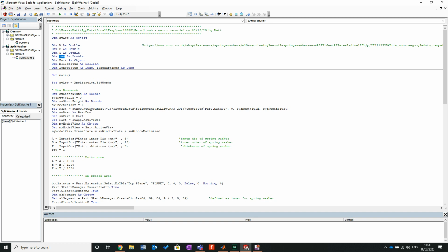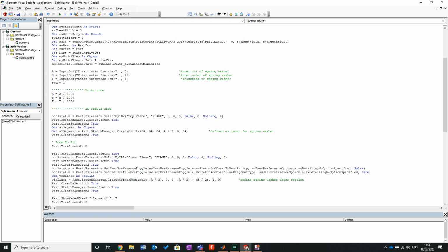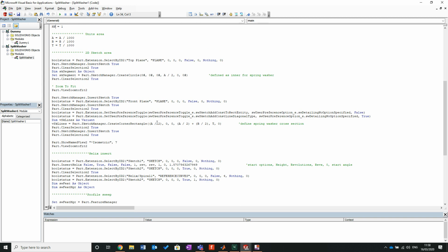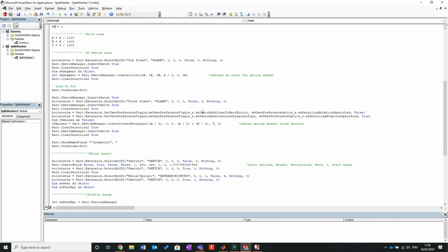We'll go HP. Then it's height and pitch. I'm going to rename it just because I think if we leave it as rev, it's going to leave a lot of confusion. It would confuse me, as I'm sure it would confuse some of you. It would confuse the living crap out of me if I left it as rev. So we need to get back down to the helix. We'll remove that and we'll go HP. Then we'll go on to the next section for it and then we'll define that as HP.